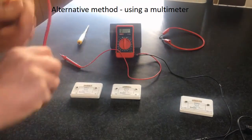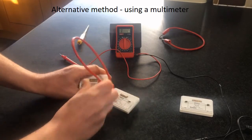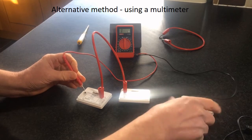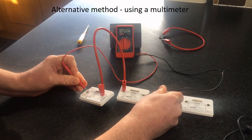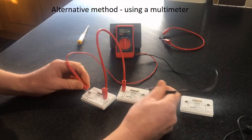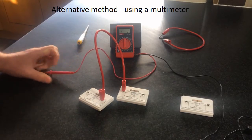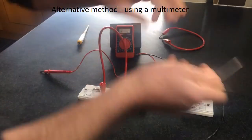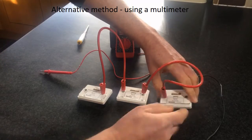We'll start off then connecting two of them in series. So we'll do the series first. So series, they're just next to each other, and then I connect on there. So let's have a look what 2 in series looks like. 20, 19.9, let's do it again. 20 ohms. So that gives 20 ohms for 2 in series. Let's put an extra one in. So now we've got 3 10 ohm resistors in series.